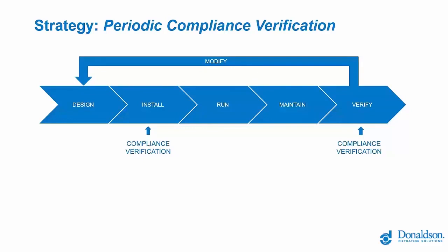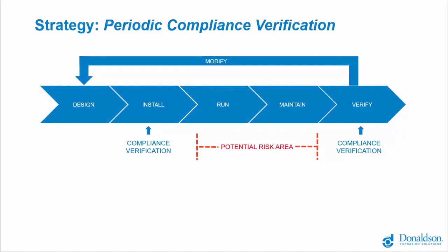So when we want to make sure that our dust collector is working the way it's designed and that we're within compliance of all of our regulations and our internal processes and procedures, we're typically going to do that anytime we install the dust collector or make a design change to it, and then when we get to that verify step at the end. That verify step might be every few weeks, every few months. It might be up to a year, depending on what regulations you're required to meet or what your internal processes require. Which means that for a lot of the time, when the dust collector is going to spend most of its time in that run-maintain mode, you're really in a risk area where you aren't sure if that dust collector is still working within its design parameters, or if there might be a problem that could be affecting the exposure of your employees, it could be affecting the environment, or you might be running outside of compliance.